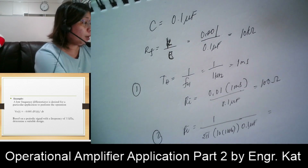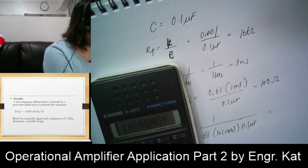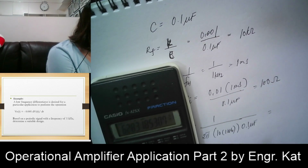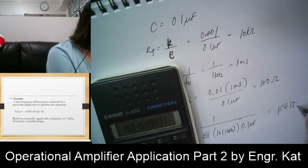Solving for this, we have 2 times pi times 10 times 1k times 0.1 micro, then we get the inverse of that. That will give you 159.15 ohms.